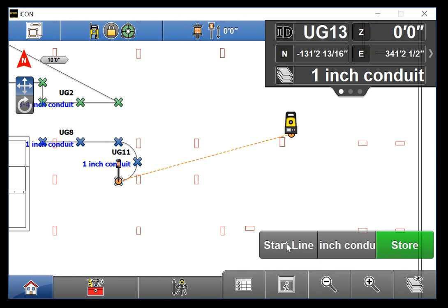As you can see, it drew a smooth transitioning arc and connected that arc to my straight line. At this point, you can keep going with your straight line by clicking Start Line again. You can close the line by clicking Close Line, or if you've finished, you can just stop.